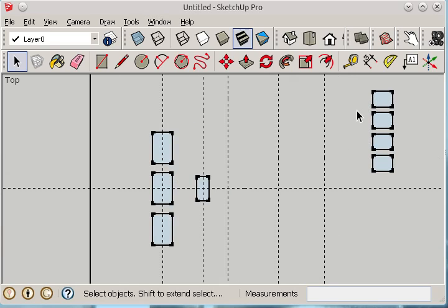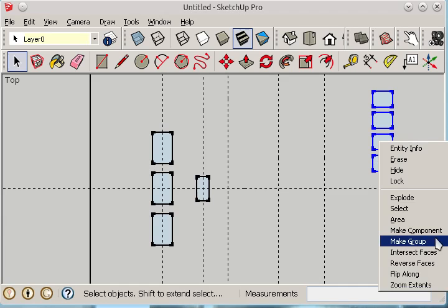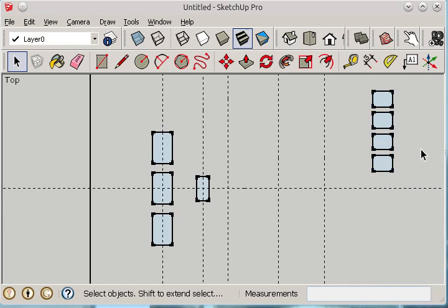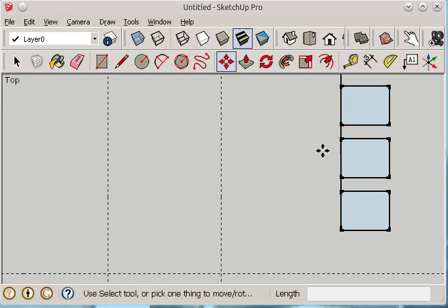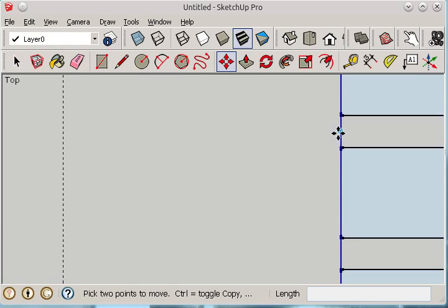Yeah, I have to do some workaround. In KiCad this could be improved: the symmetry or alignment function on the symmetry line. I have to do a workaround here by making a group, and drawing a line over this group, so I can now snap to the middle of the group.